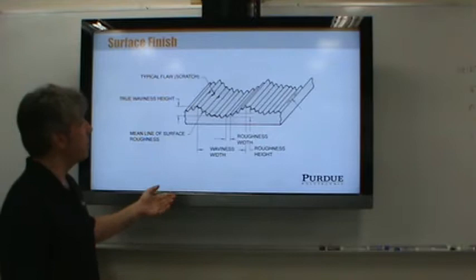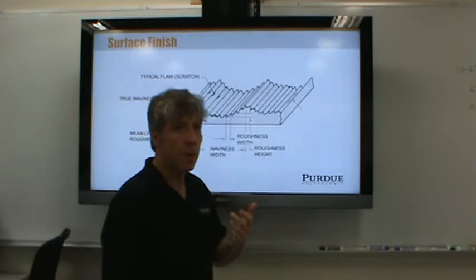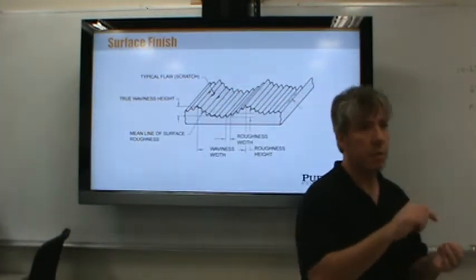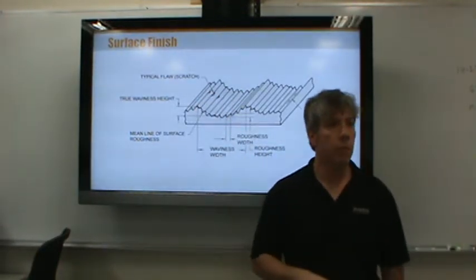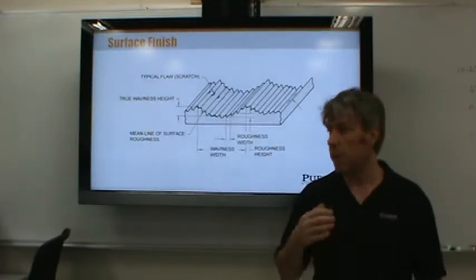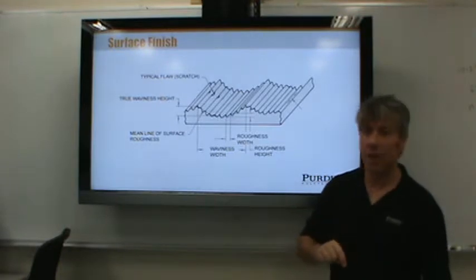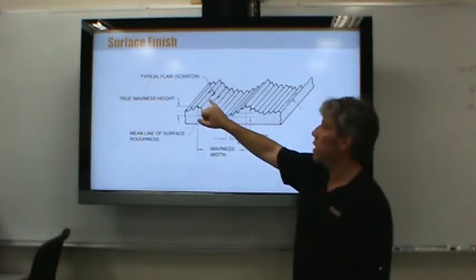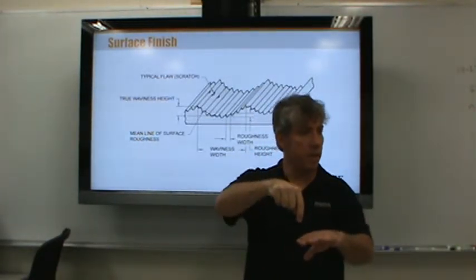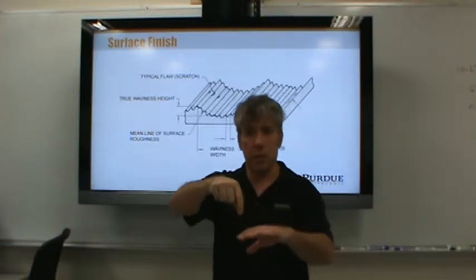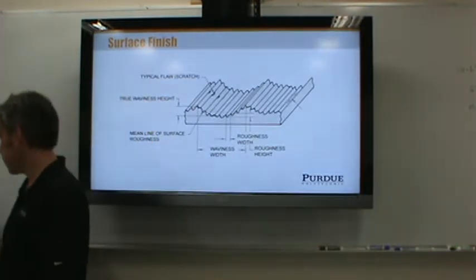But yeah, an album is an example of this. You probably know that sometimes albums get scratched, and when they do, the sound degrades. It'll go over that scratch and it'll make it pop every time. That's because the needle is actually detecting this. There are many ways now to detect it; you can use lasers and light, and you can use lasers to read albums also, which is kind of interesting. But one of the ways to detect surface roughness is by dragging a very fine needle on a very balanced arm that detects motion as the needle rides up and down in all of the waves. That's one way of measuring surface roughness.